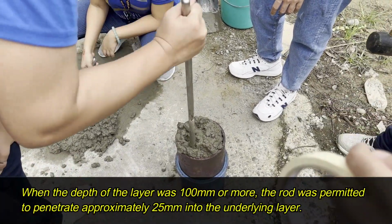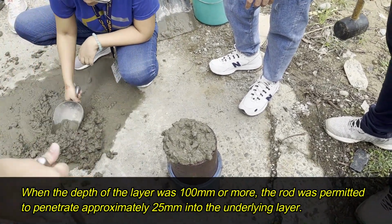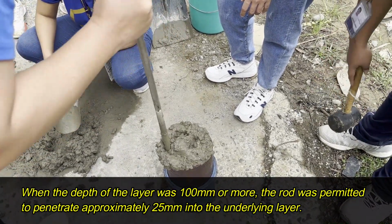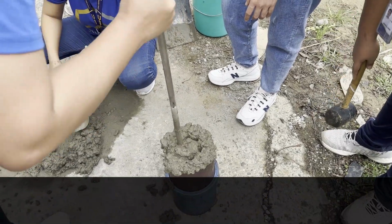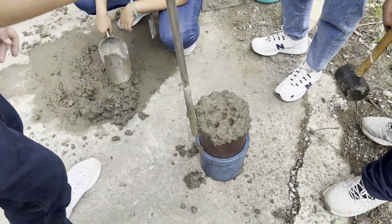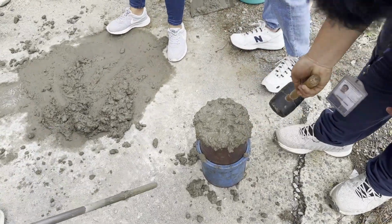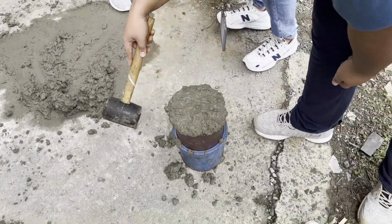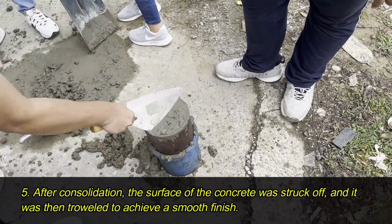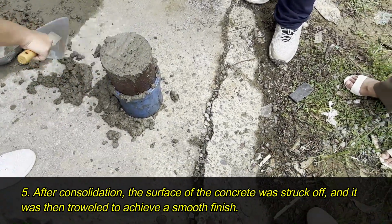When the depth of the layer was 100 mm or more, the rod was permitted to penetrate approximately 25 mm into the underlying layer. Number 5. After consolidation, the surface of the concrete was struck off and it was then troweled to achieve a smooth finish.